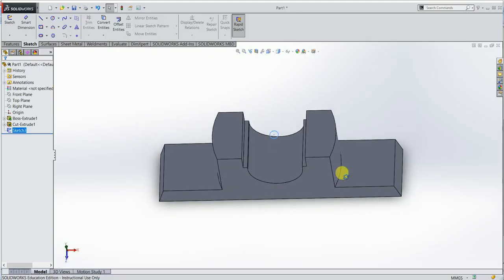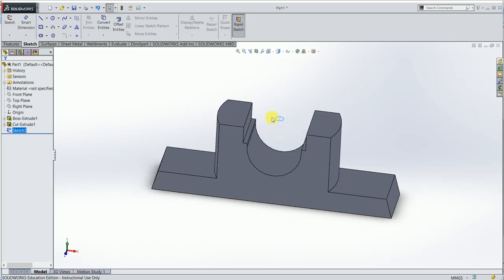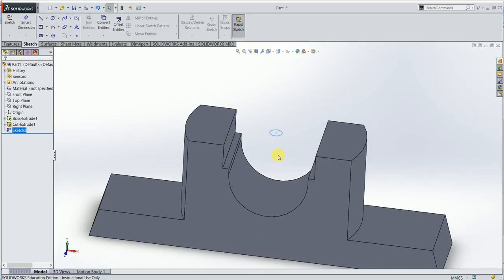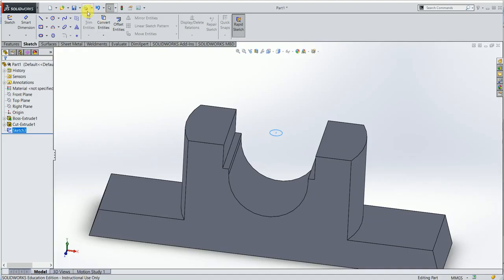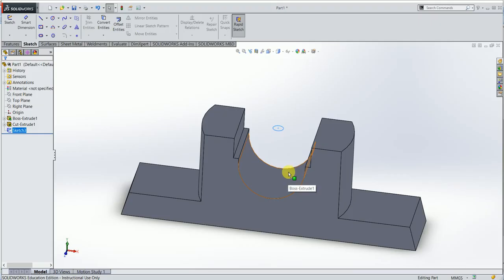Now when you tilt the model, you can see this is where we have created this circle. I have created this circle to use as my reference for placing the hole. Already this portion is hollow, so there is no need to make a hole in this hollow portion. We need to make a hole of diameter 6 mm and depth 6 mm here, and that particular hole should have a V bottom. You need to remember, we cannot place the hole on curved surfaces. We need to start the hole from the flat surface.